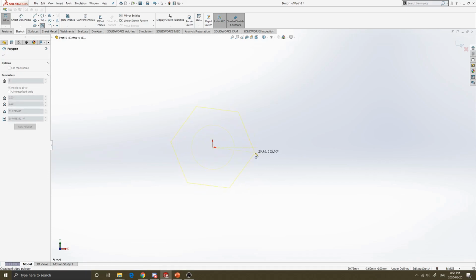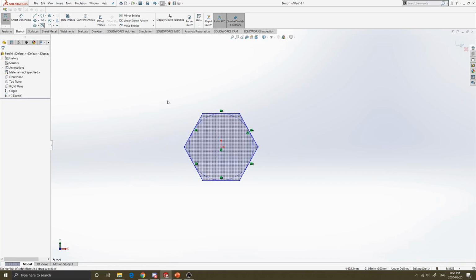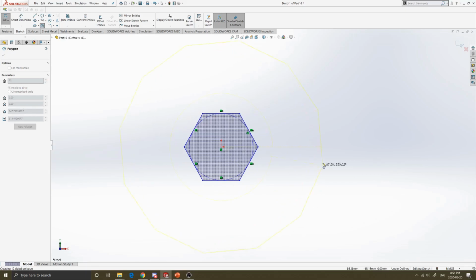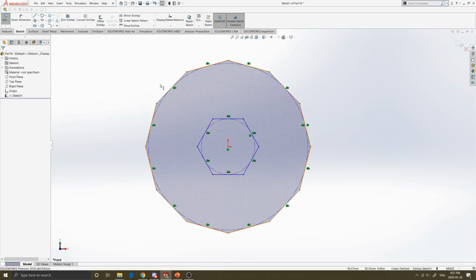Another one is polygon, so you can make hex heads really quickly instead of drawing the whole thing from scratch. It's really a pain in the butt. The nice thing about this is you can actually do as many corners as you want. So let's say you can go over to those left bar right here. I want, let's say, 12 points instead, because why not? Now, as you can see, this has 12 lines instead of 6. And I think all you need to define is the radius.